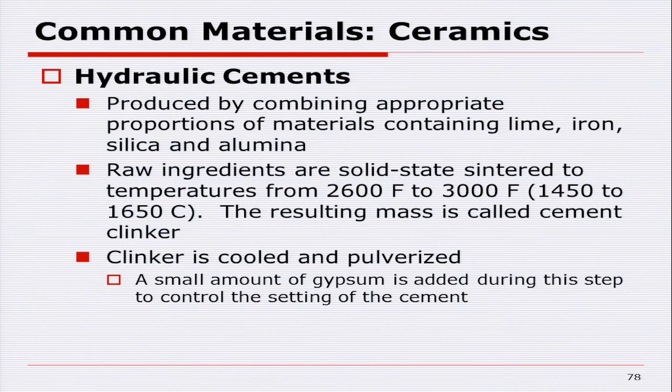The one thing I was going to say about clay, when you're working with clay to make pots and so forth, is that to mold it, it has to have a fairly high moisture content for you to shape it like you want. And you need to let that water evaporate off a little bit. If you've made pots, you'll stick it in the kiln, but you only heat it up at a very low temperature, or in a drying oven, to try to drive off some of that moisture. And the thing is going to shrink as you do that. As you drive off moisture, clay is going to shrink, just like soil.